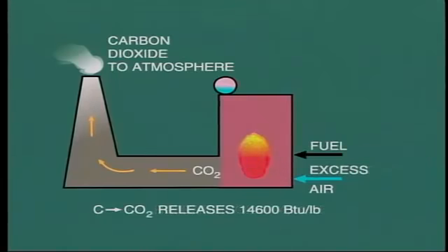In order to ensure that combustion of the fuel is complete in practice, we need to provide excess air. The precise amount of excess air over the theoretical amount calculated really depends upon the type of firing equipment and the fuel itself.